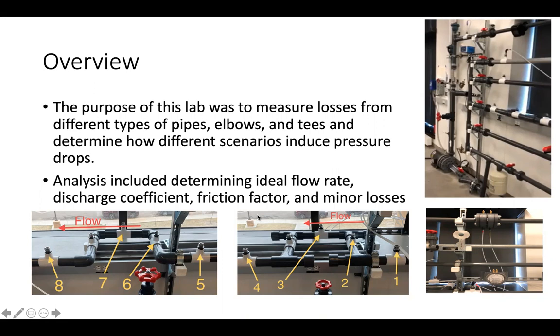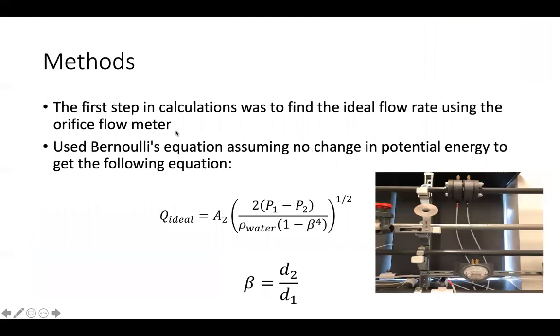The flow rate throughout the top branch was measured with a digital flow meter and an orifice plate. There was a differential pressure taken before and after the orifice plate to calculate the overall flow rate. Pressure gauges were given at the inlet and outlet of the pump, which allowed us to find a differential pressure of the whole system.